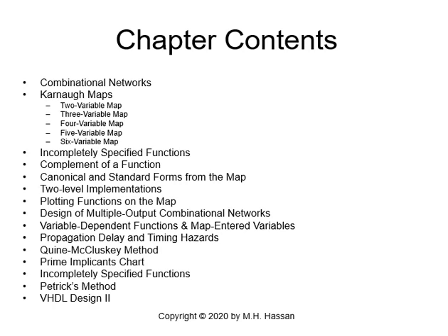functions on the map, design of multiple output combinational networks, variable-dependent functions and map-entered variables, propagation delay and timing hazards, Quine-McCluskey method for minimization, prime implicant chart, incompletely specified functions, matrix method, and we'll look at VHDL design too.